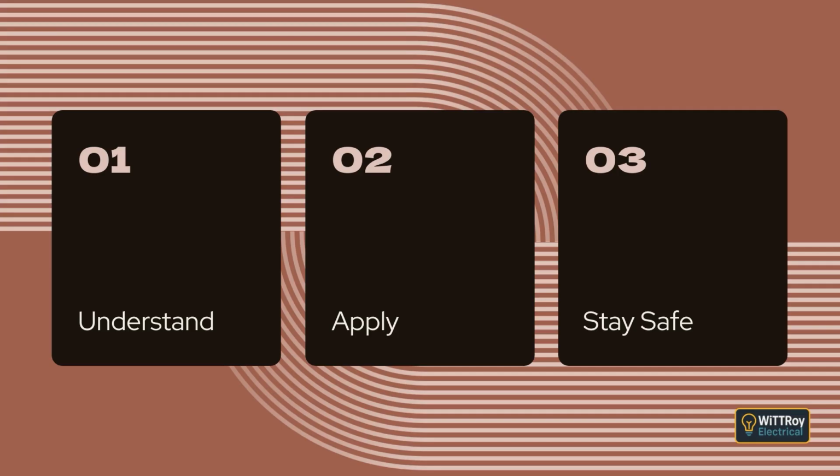Clause 3.8 Identification. This clause introduces the requirement to clearly identify conductors so their function as active, neutral, earthing, or equipotential bonding is unmistakable. Clause 3.8.1 General. Installation wiring must be clearly identified so anyone working on the installation can immediately recognize each conductor's purpose.